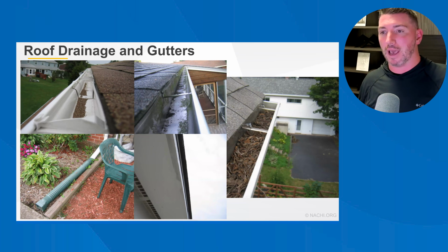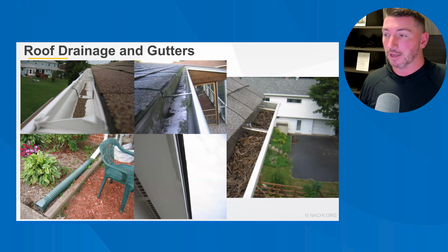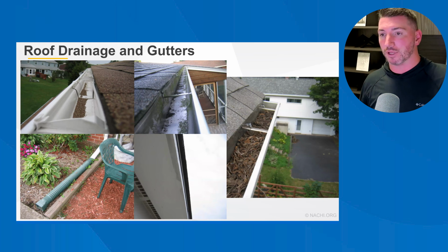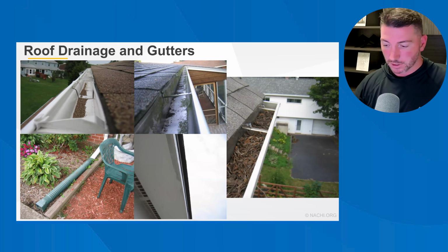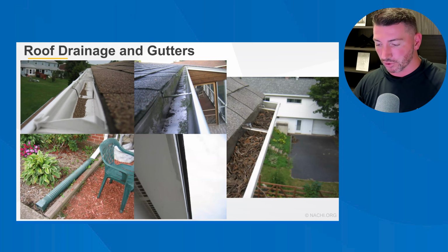Now, that's not going to happen in a very light trickle because the water is just slowly running off the roof. But once you get a really severe storm, now the water is going to be running and just overshooting the gutter completely, eroding the ground underneath it and possibly causing a foundation issue. So typical gutter systems hold up better when the brackets are spiked or screwed through the fascia and into the rafter tails, not just into the 3/4 inch fascia board.